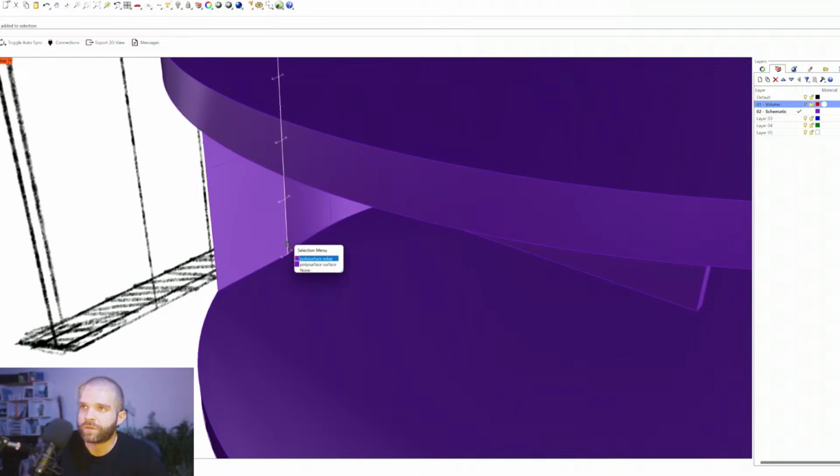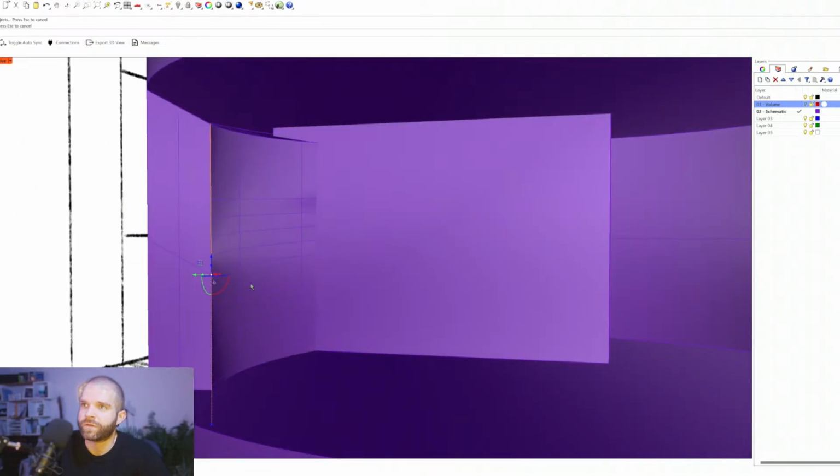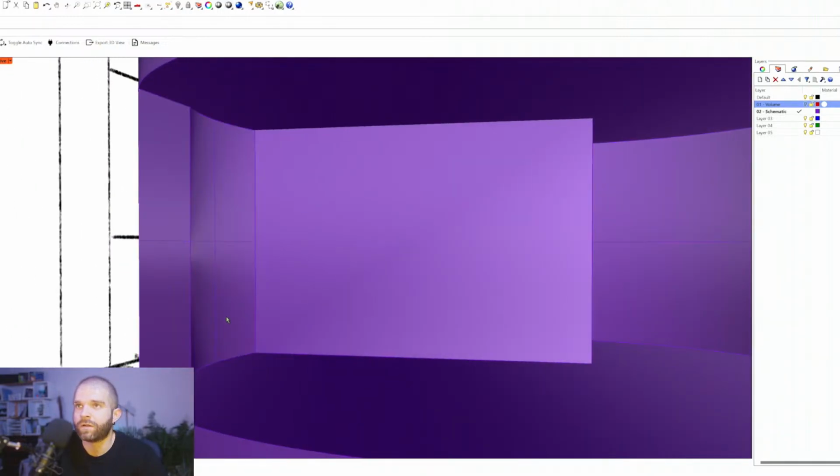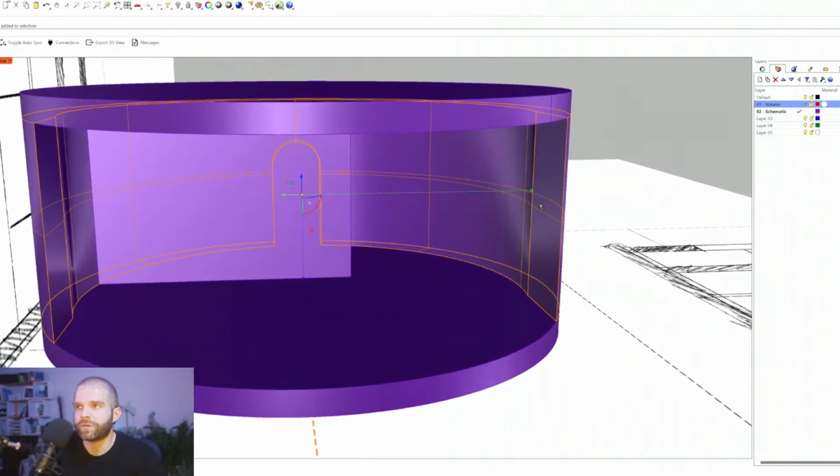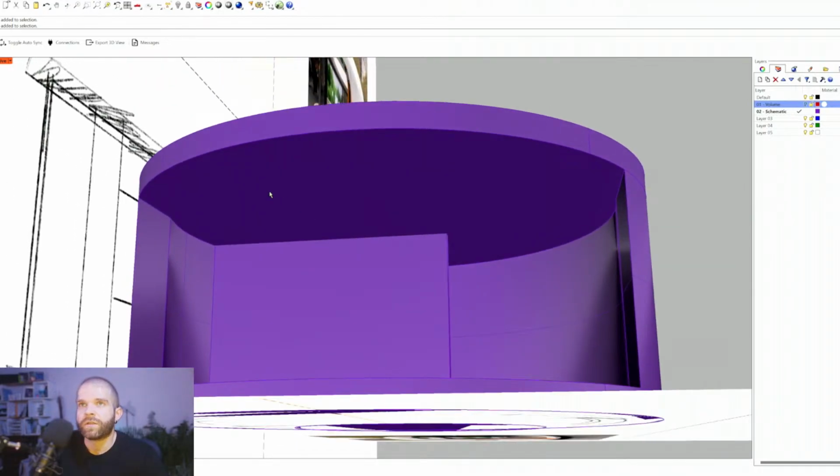All right, so this is our glass, and then this little edge here is our circle, right? So I can't really move this along the circle because it'll distort the rest of the wall very nastily. So we kind of have to rebuild that feature there and ultimately do a Boolean union onto the side here. So I will do Control Shift click. So like this face. Oh, just kidding. I do want to isolate that face, but the command I'm about to use, which is dupe face border, doesn't require me to select it beforehand.